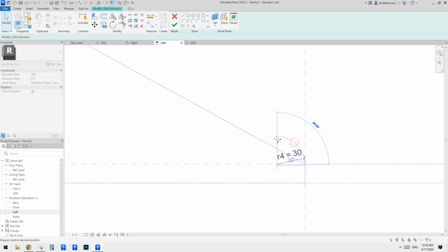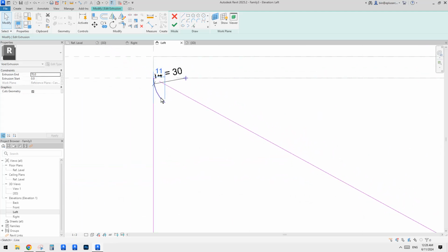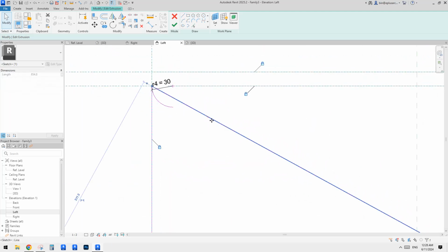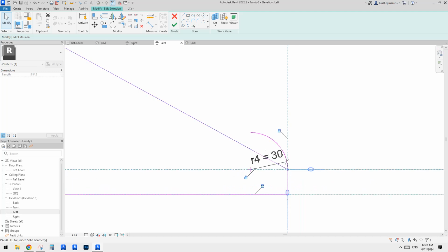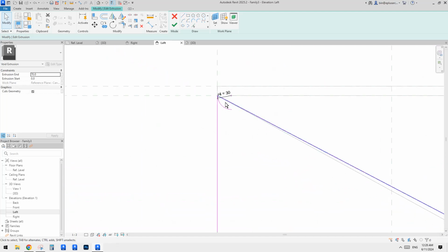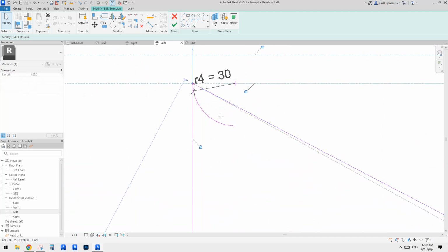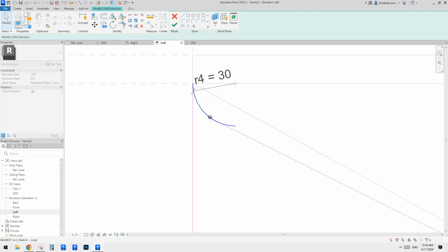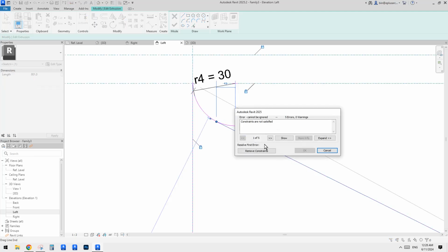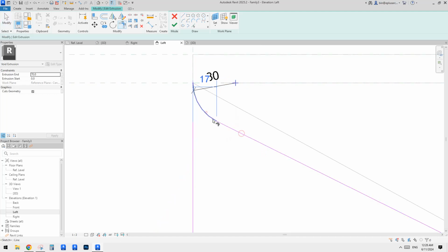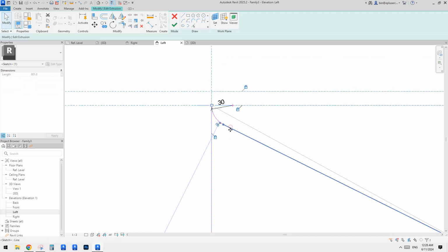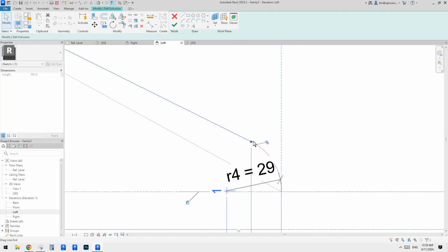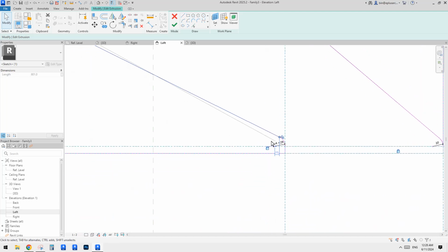Maybe just extend this arc a little bit. So same to here, and then select this line, drag this onto tangent, trim, TR, select tangent, lock tangent, and same here. Select this, drag this. Looks like we have some issue, but don't worry. Remove constraint for now. Trim, lock tangent, and we might need to, yeah, so still locked, so that's good.